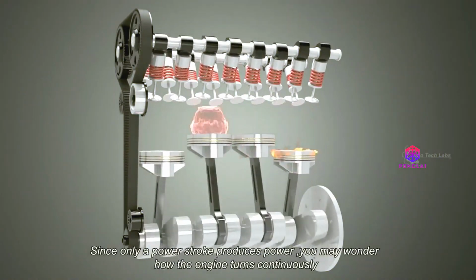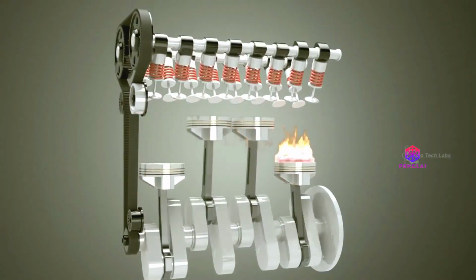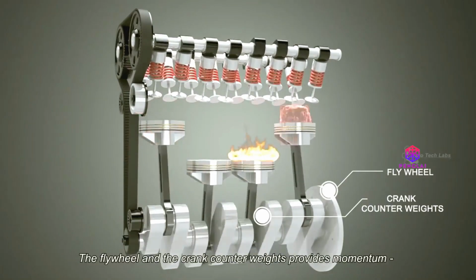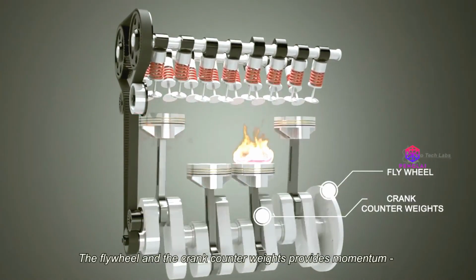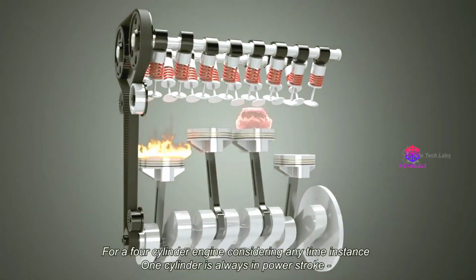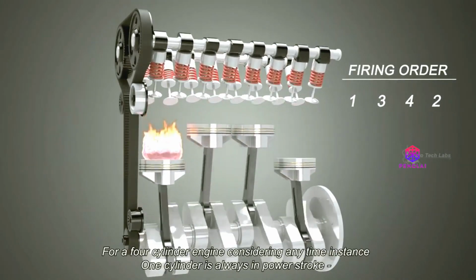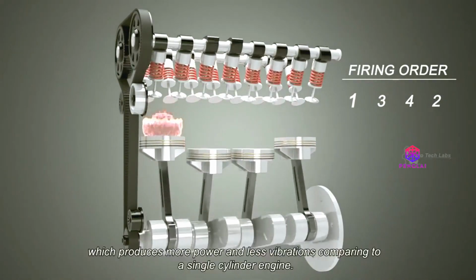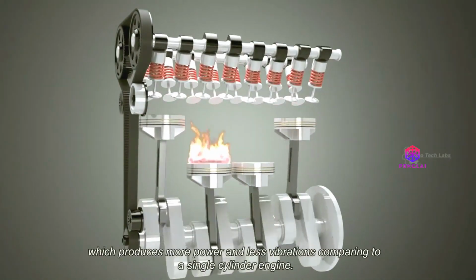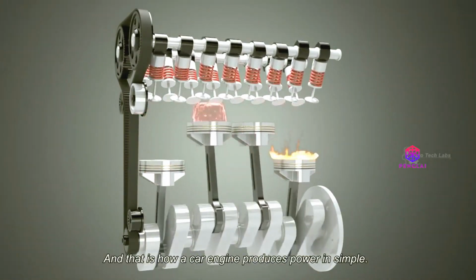Since only a power stroke produces power, you may wonder how the engine turns continuously. Well, the answer is in the crank itself. The flywheel and the crank counterweights provide momentum, which keeps the crankshaft from stopping immediately. For a 4-cylinder engine, considering any time instance, one cylinder is always in the power stroke, which produces more power and less vibration compared to a single-cylinder engine. And that is how a car engine produces power, in simple terms.